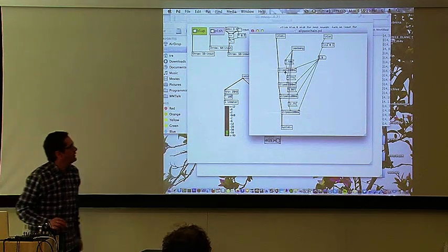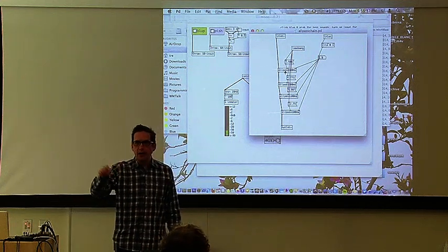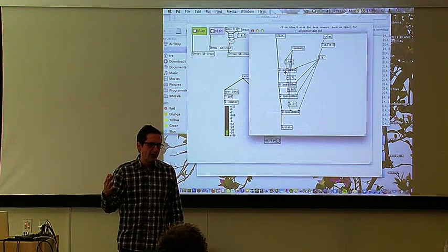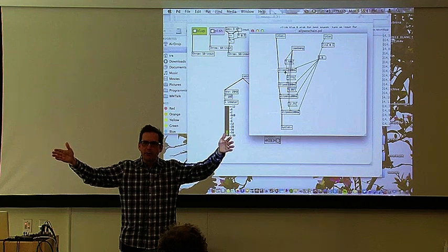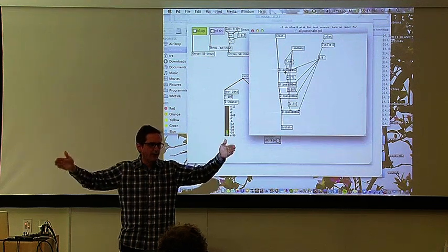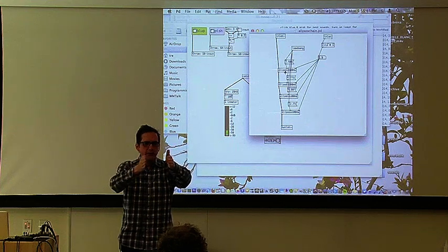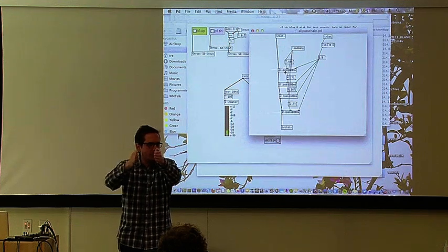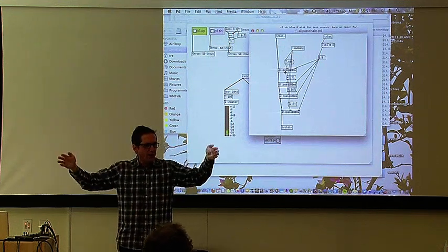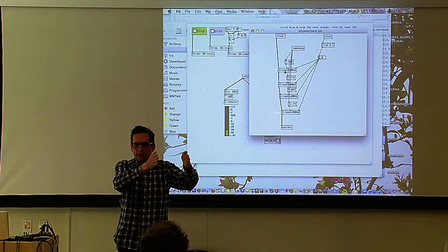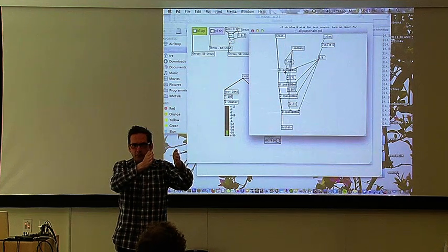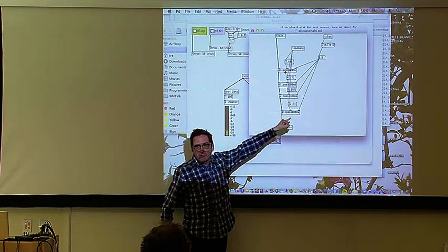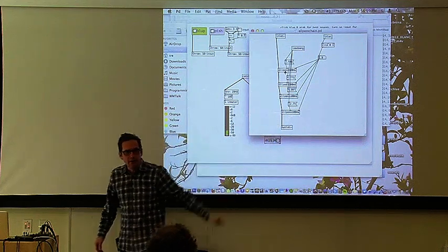The danger with all-pass filters is that they're based on a feedback mechanism. So if you turn the gain up too high, they will start ringing. Though if you look at their spectra over the whole term of the all-pass filter, you'll find that it's a flat frequency response. What happens is your ear focuses on short periods at a time, and so you hear the pitched portions at moments. So you really need to consider your own perception of pitchedness from the all-pass filters. This is your guide to how long you can make the all-pass filter and how much gain you can give the network.